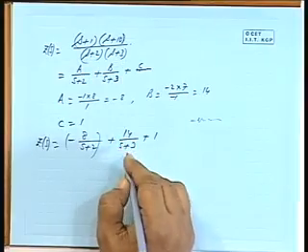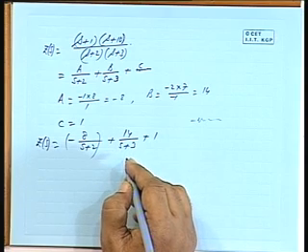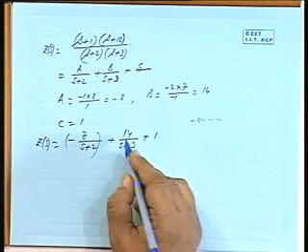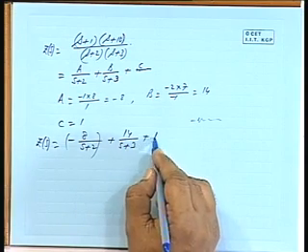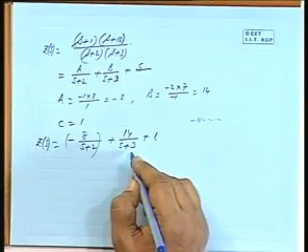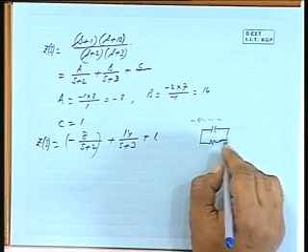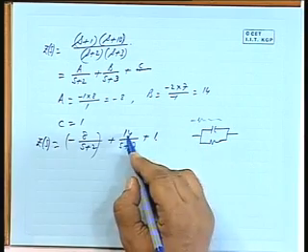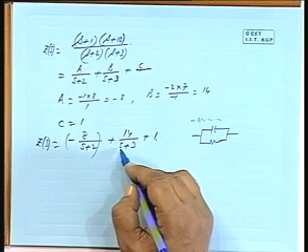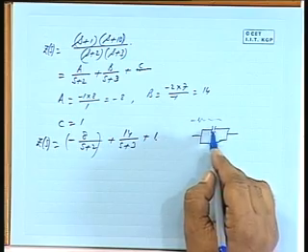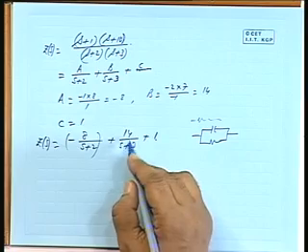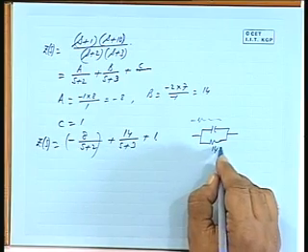I am bringing them to very small simple form. 14 by S plus 3 plus 1. This one I can realize as 1 ohm resistance. 14 by S plus 3 I can realize by RC combination. You put S tending to 0. So, S tending to 0 will be blocking this capacitor. So, 14 by 3 is the resistance.